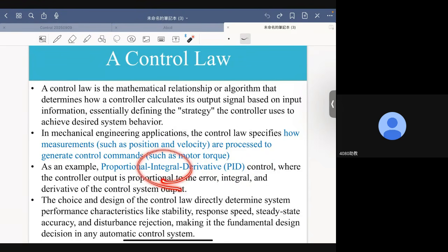And the final part, the third part of the PID control law, is integral. That is, my control action for this part is not just based on the current status of the output error. I look back at the history of the output error. Output error sometimes is positive, sometimes is negative. I integrate them to see its average past history profile. So one is the current condition, one is the changing rate, and the other is the past history. When you put those three ingredients together, you come out with a PID control.